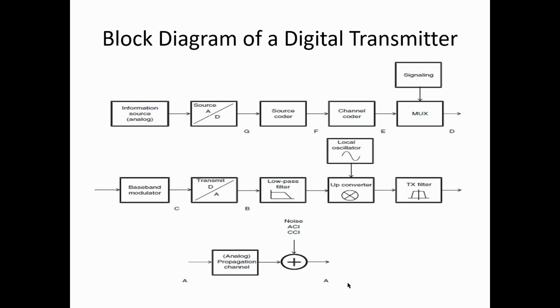Already the low pass filter eliminates the out of spectral components, but after the low pass filter we are again up converting the signal. After up converting the signal, we need to ensure that our signal is within the band of spectrum. So again the out of spectral components are eliminated here. This filter eliminates the out of spectral components that occur due to the upconversion. So these are the functionalities which occur at the transmission end. Each block has a unique functionality, and each is doing its own functionality for upconverting the signal and transmitting the signal to free space.